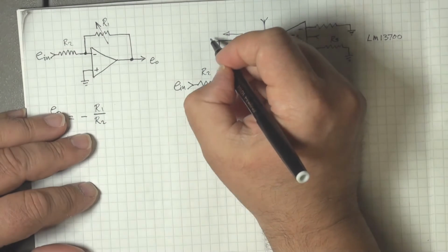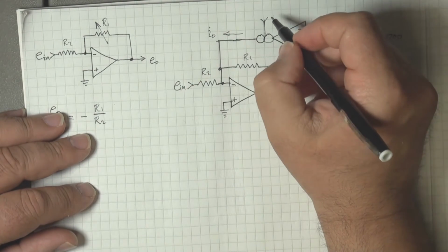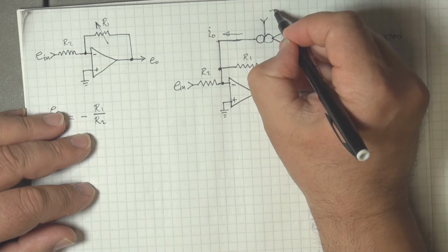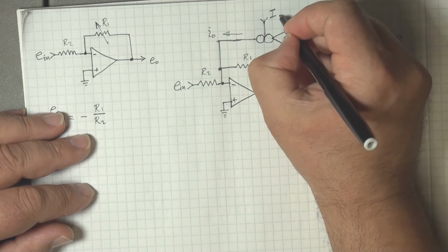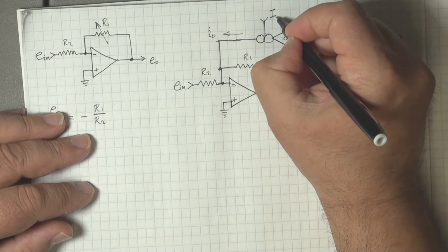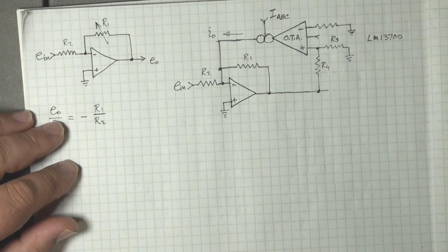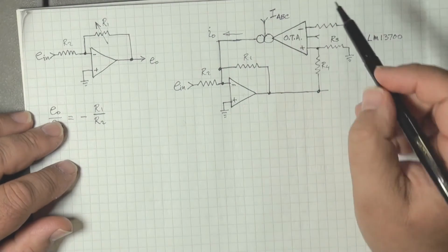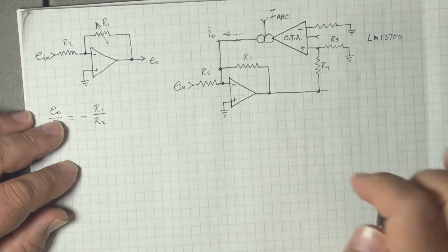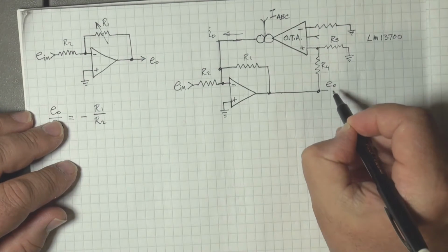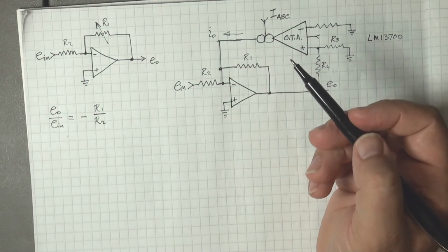And the output current, say I_O, is directly controlled by an input current into this control pin called the amplifier bias current. So as the amplifier bias current goes up, the gain, the transconductance gain in other words, goes up, and for any given signal at the input level, the output current goes up.